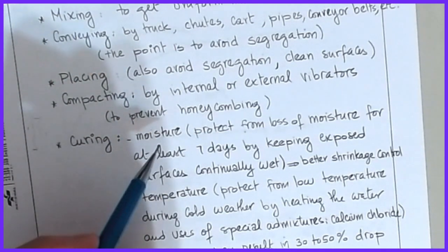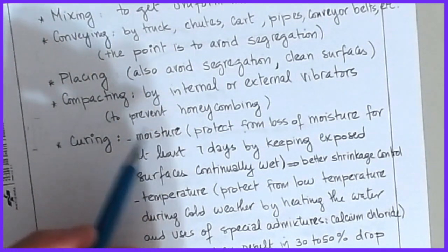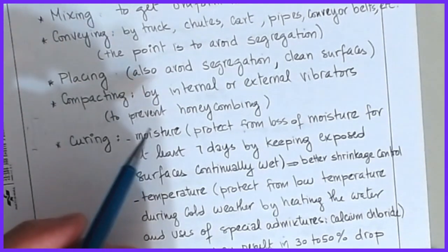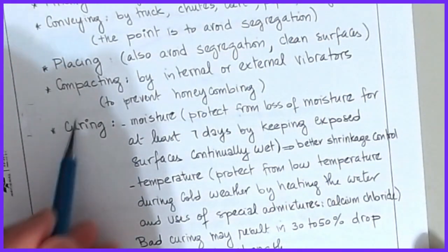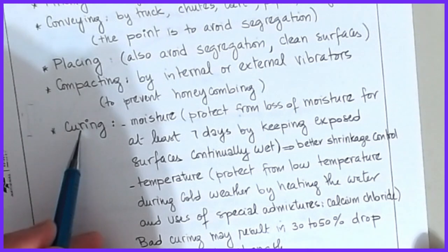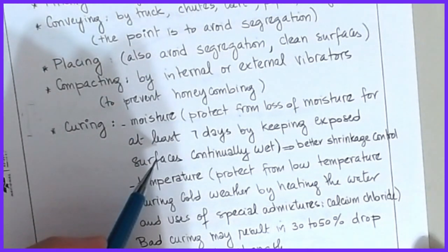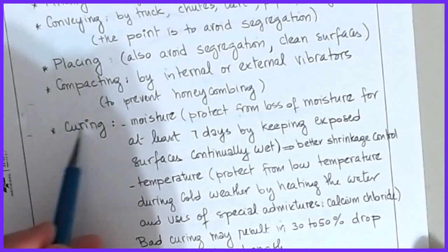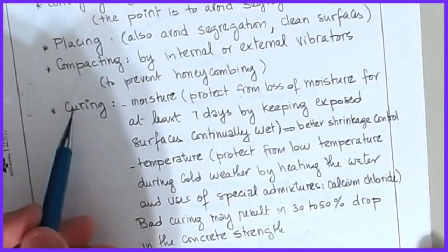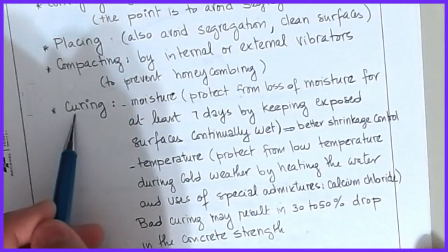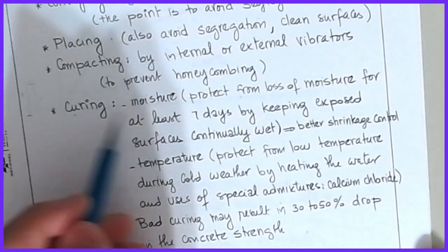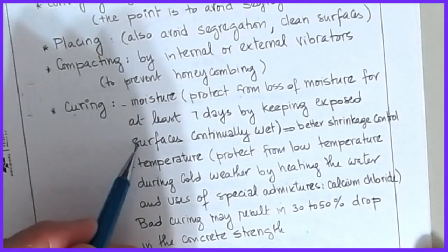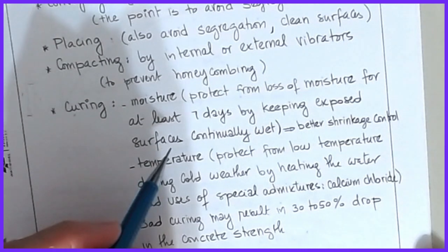If there's no concrete, because there's an air pocket, then I can't have stress transfer across an air pocket. Curing is, once it's placed, it's got to sit undisturbed, usually for at least 7 days before being exposed. But more often, we try to have curing conditions in place for a lot longer than that. Better curing helps control moisture evaporation off the surface, which usually leads to better shrinkage control.